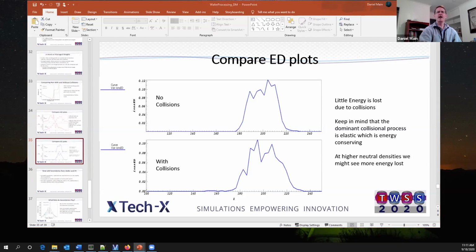So Robert asked, how many Debye lengths is the optimal focus ring height? I don't know the answer to that. I think a lot of this is trial and error, which is why you need simulations. So that would just be a question of setting up your simulations with some geometry in mind, and then just changing one thing at a time and running these simulations.